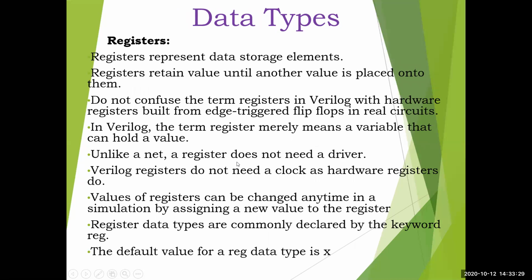Second data types, registers. Okay. So there is a clear cut difference between nets and registers. They are exactly contradictory. Nets will not store any elements, whereas registers represent data storage elements. They are not hardware registers. They contain the value for a longer period of time.